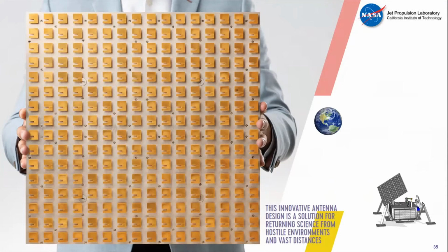It's entirely made of metal. It can survive and operate at cryogenic temperature, and it can also survive the high radiation environment of Europa. When I say survive, you want to make sure that the antenna is not consistently going to discharge, because these discharges are going to propagate to the telecommunication subsystem, and it will damage some of the critical hardware.